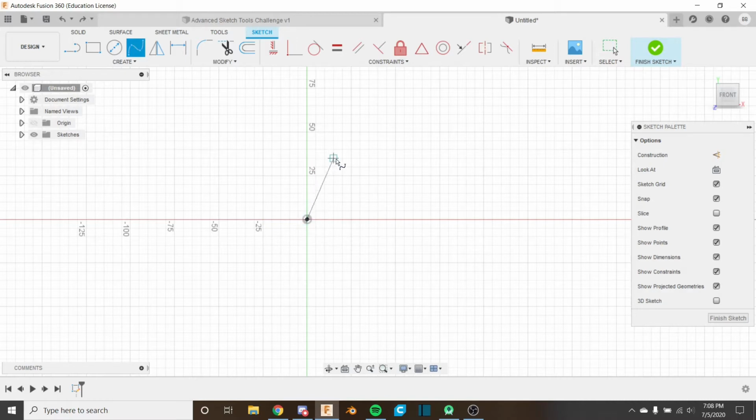So if I start here, it's now asking for the next point. And once I place this next point, we'll be able to see some interesting stuff happening here. Instead of interpolating in a straight line between these points, the interpolation is based on the points that follow it and come before this point. So if I place a point directly in line with the first two knots, it will create a straight line. But if I deviate it slightly, it will begin to curve and interpolate between these points smoothly. So I can go ahead placing points, and the curve will always pass through the points.